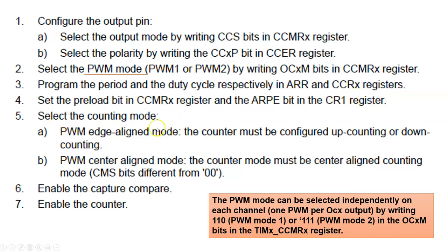Select the counting mode. Remember we talked about how you could do an up count, a down count, or a center align count mode when we talked last video about timer output compare. And then we enable capture compare, enable counter.